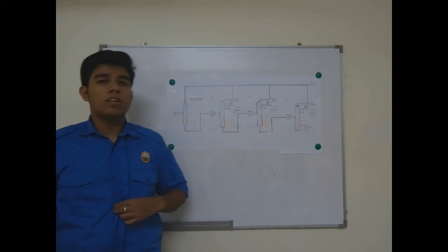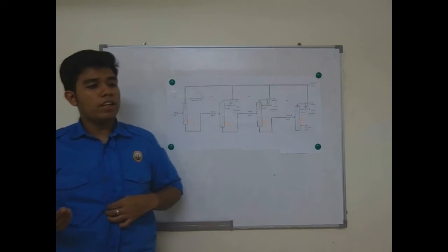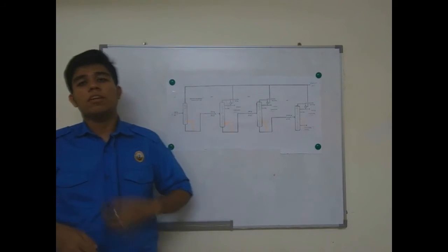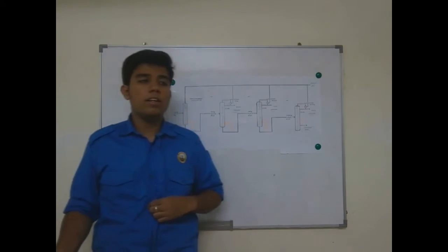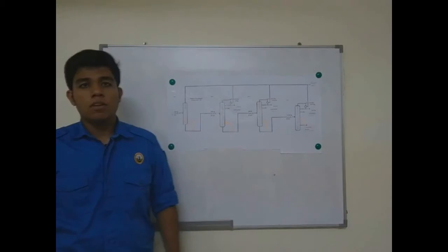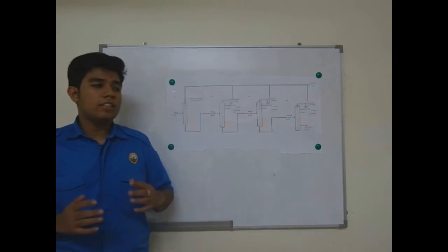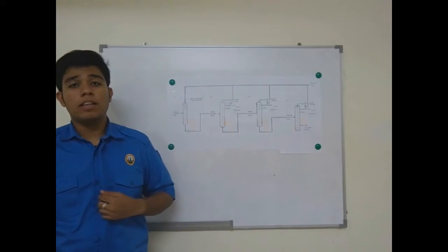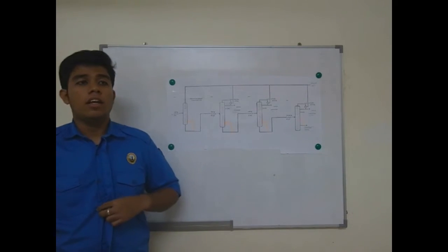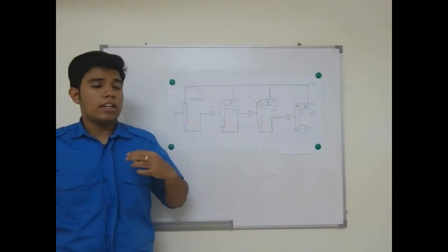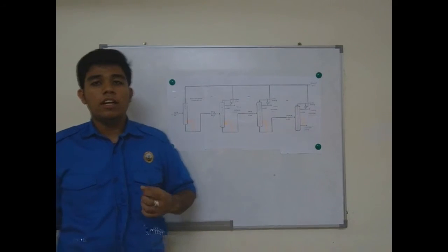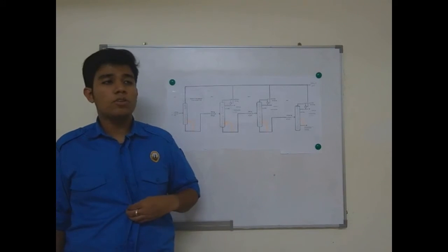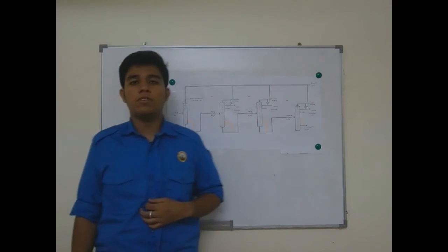So we can say that most of the heat in a large diameter column will be released to the surroundings compared to a small diameter column. If we decrease the diameter of the column, the temperature is easier to maintain, and the triglyceride or substance can be separated properly according to the boiling point. That's all. Thank you.